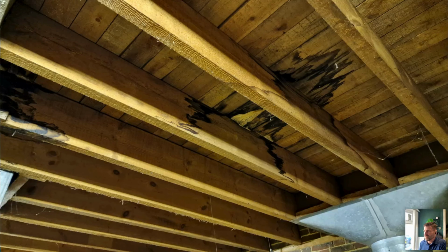So it's more difficult to identify a close boarded deck unless you really know what you're looking for. But it's always better to go underneath first and see what the deck is from the underside, A, to determine what it is, and B, to determine whether it's safe to traffic.